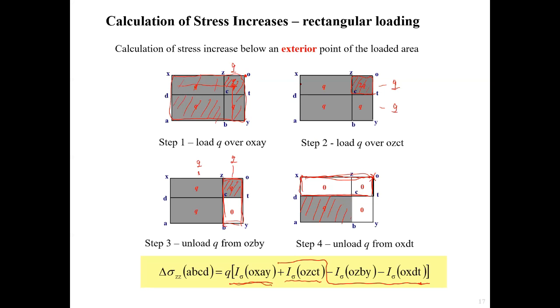That's how it works. Otherwise, it doesn't work. So you assume you apply the Q for this big rectangle. So actually there's no surcharge or no load. So you have to take out the assumed part. So you take out this part and you take out this part. So now here that's become 0 and here becomes 0, which means no load.